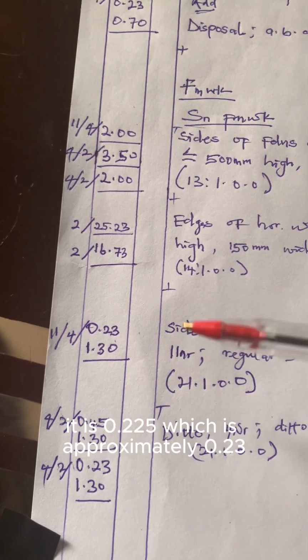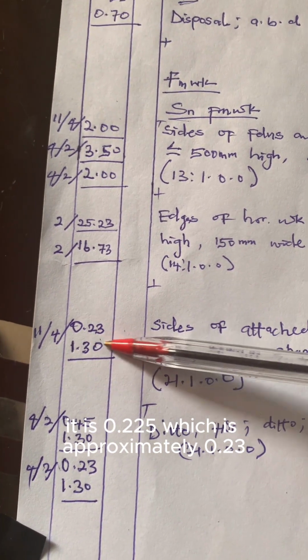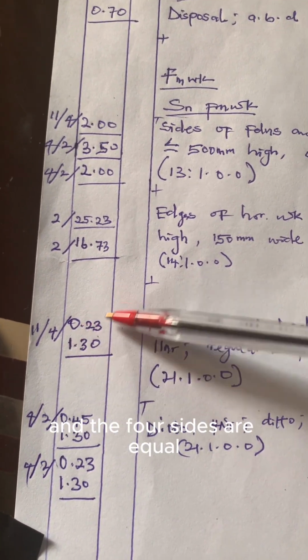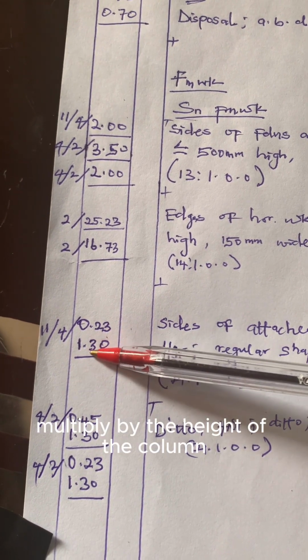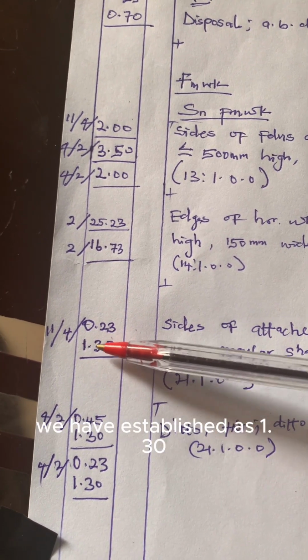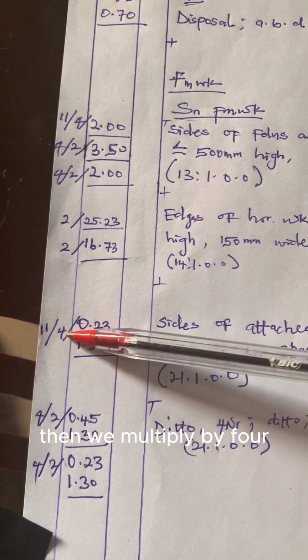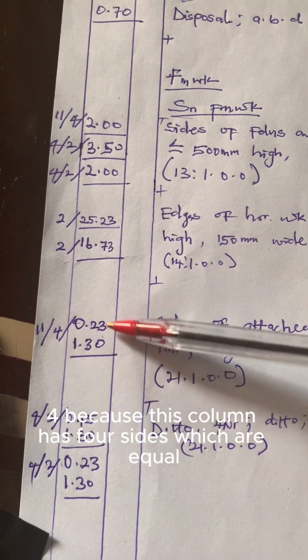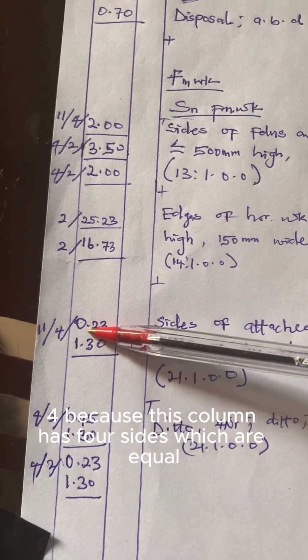In meter it is 0.225, which is approximately 0.23, and the 4 sides are equal. So we just pick one side, multiply by the height of the column we have established as 1.30, then we multiply by 4 because this column has 4 sides which are equal.